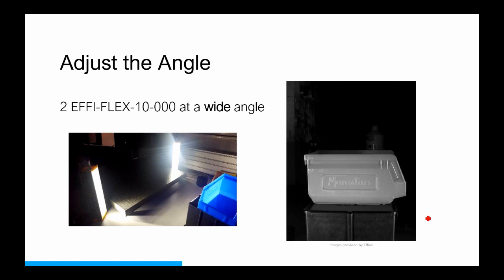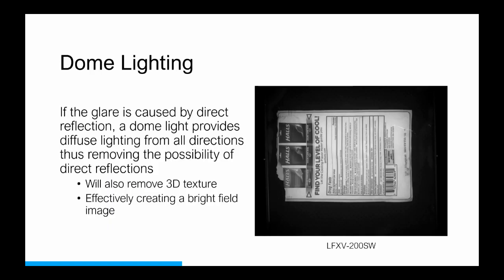So while it might be an even image in one example, with no angle of reflectance into my camera, the next piece that comes down might have that perfect angle where it does reflect the light back into my camera, and the next image might have glare. When we have more inconsistencies in the parts as they come through, that's when we need to go to a different type of light altogether. That's when we want to talk about using a dome light.